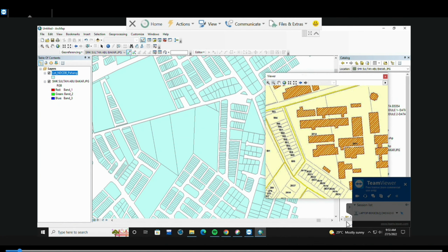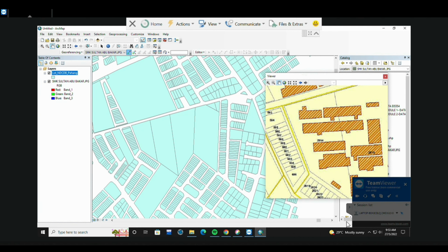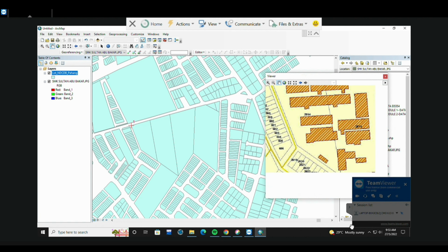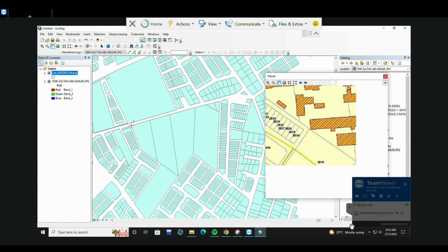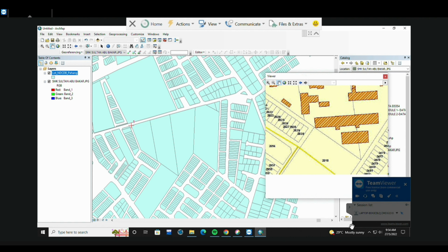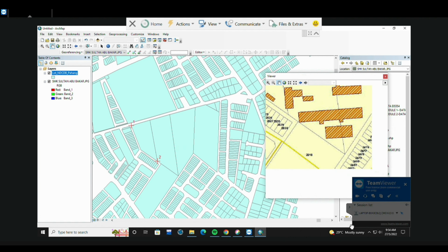Next, we need to identify which area to do georeferencing for both layers. The georeferencing process should be done on the reference data layer lot and DCDB Pahang SHP, because layer lot and DCDB Pahang SHP are on the real coordinates of the Earth's surface. At least plot 4 control points during the georeferencing process. On the georeferencing toolbar, add control points on the lot building SMK Sultan Abu Bakar and make sure you plot the control points on the same position for both layers.